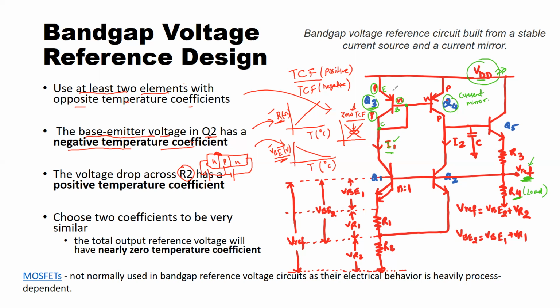because the base emitter junction voltage, that is the mod of VBE here, is equal to the VBE of this transistor Q4. Assuming Q3 and Q4 are exactly of the same type from the same manufacturer, I will mirror the same magnitude of I1 into transistor Q4, which is called I2.